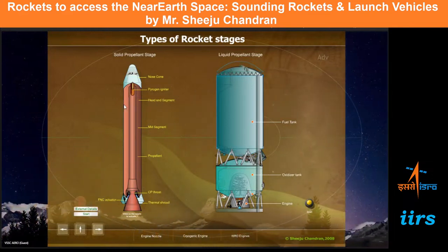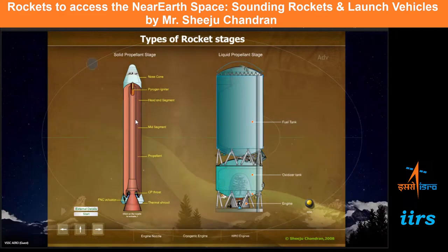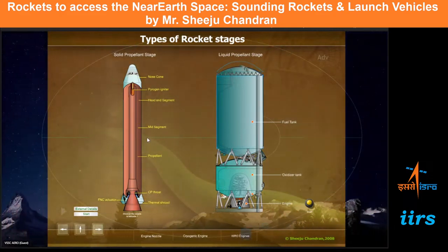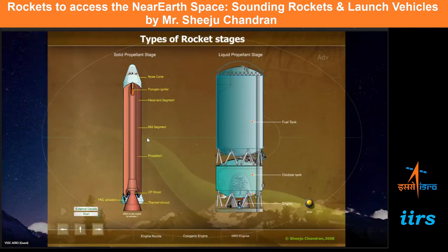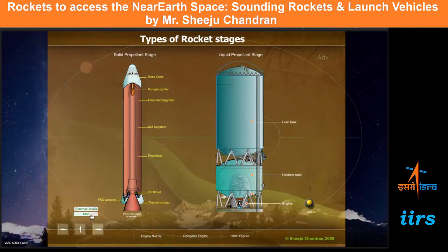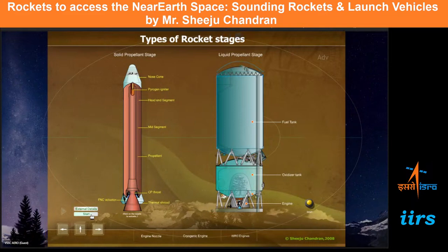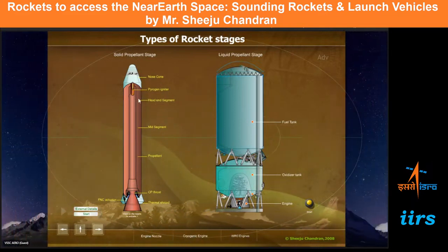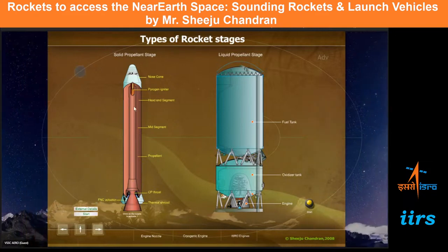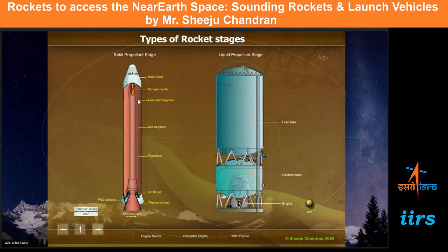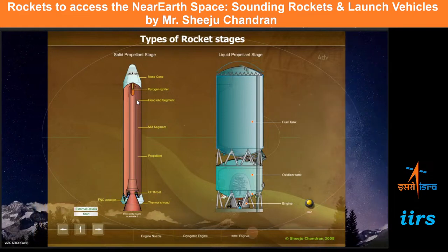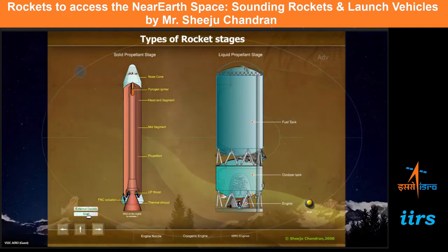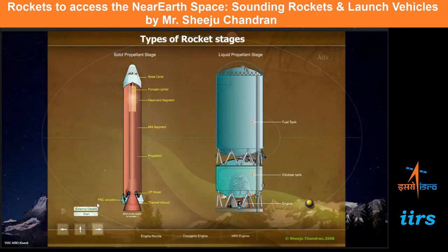That's what you see in this picture in a brownish form. In the core area of the rocket, there will be an empty space for the gases to come. And then if I give a start command, you can just see the rocket will be started by a system of equipment called igniters. The igniter will allow the entire rocket to catch fire inside, and then all the combustion products produced will be thrown out through the nozzle. And in that process, it will be developing thrust, as you are seeing now.